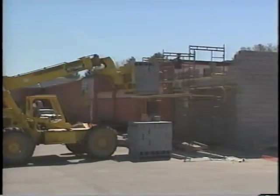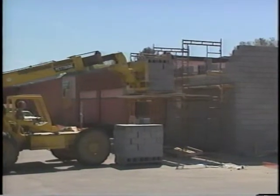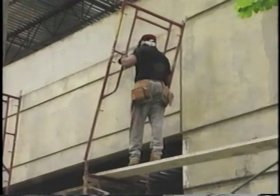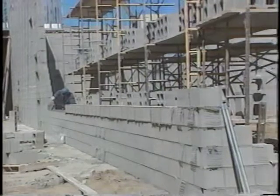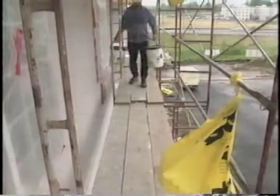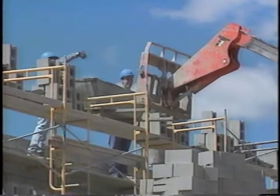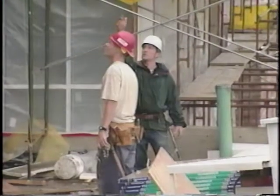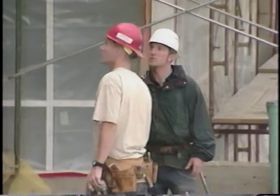A scaffold is required to support its own weight and 4 times the maximum intended load. The load capacity of a scaffold system varies with its design and application. Never overload the scaffold or a single platform of the scaffold. To prevent deflection of the planks, evenly distribute the loads. Where point loading is necessary, it should be directed over verticals or horizontal supports. If you have questions concerning the capacity of the scaffold, check with a competent person.